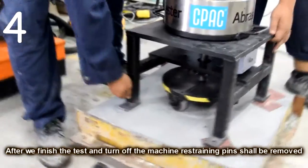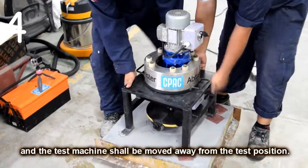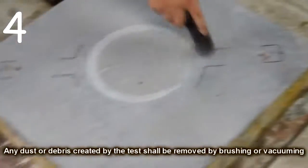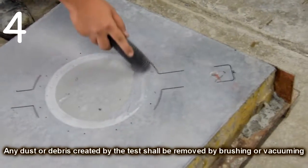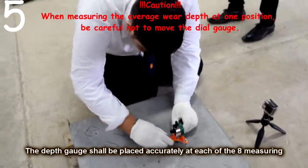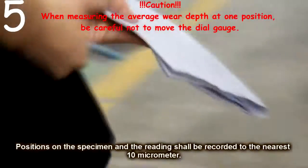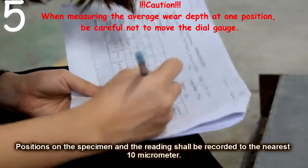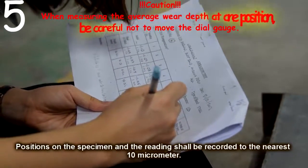The retaining pin shall be removed and the test machine shall be moved away from the test position. Any dust or debris created by the test shall be removed by brushing or vacuuming. Depth gauge shall be placed accurately at the edge of each measuring position on the specimen, and the reading shall be recorded to the nearest 10 micrometer.